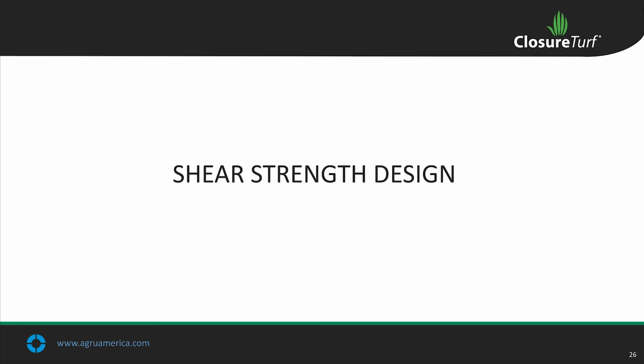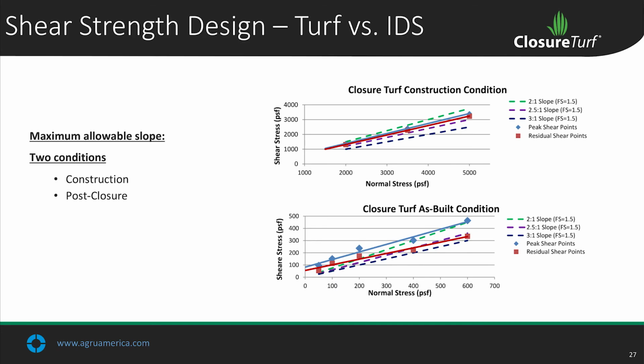So that's what this site looks like as built. And then here's its configuration as compared to the previous slide. It's all sheet flow on the slopes, down to a perimeter channel, down to a now blue detention pond because that water's pretty much clear. And the only thing they need to do is check the peak flow off the site, which is not as big a concern as it would have been otherwise with all the concentrated flow in the previous example of this figure here.